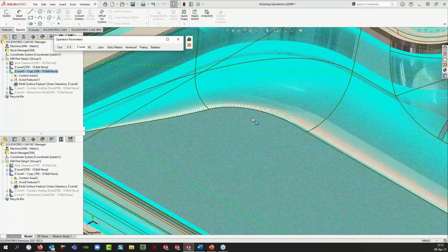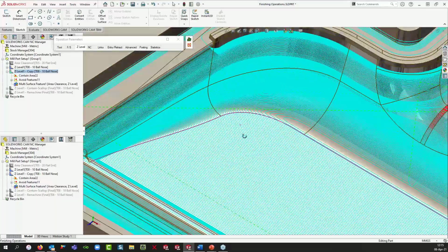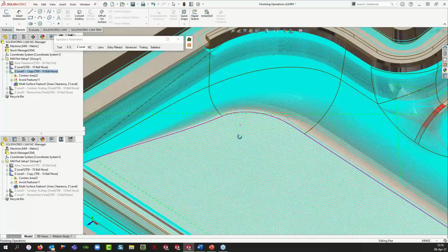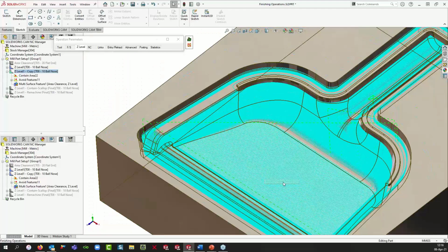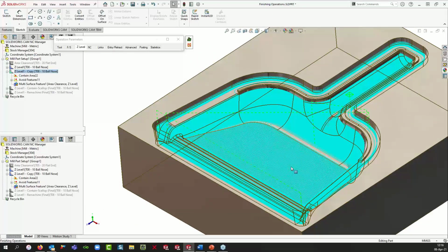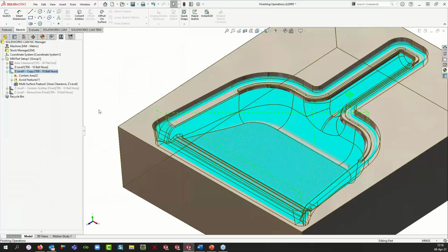So you can see just by making those small changes, you're actually going to see a much tighter toolpath. Okay, and it's going to take away all of the excessive amount of material, minimize the extreme step over, and of course any kind of rework that's needed once the tool is off the machine. All right, so we'll hit OK, and then we'll make it official here.